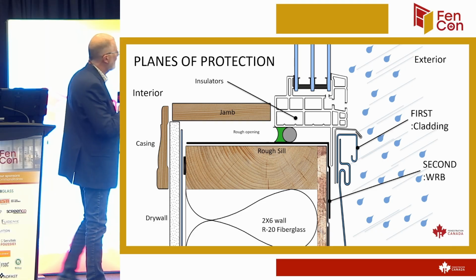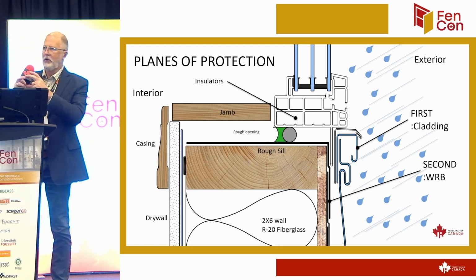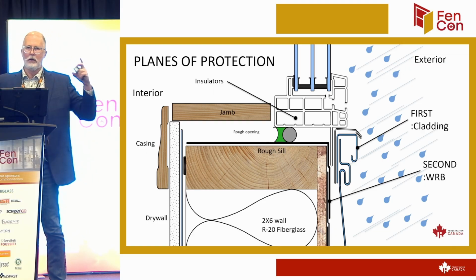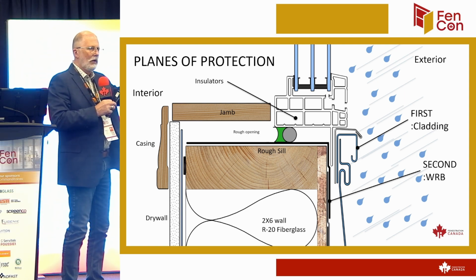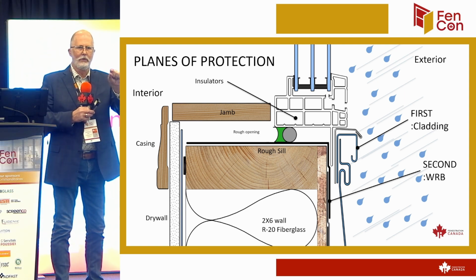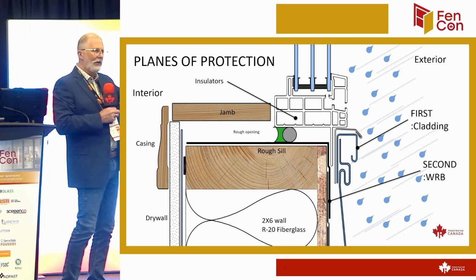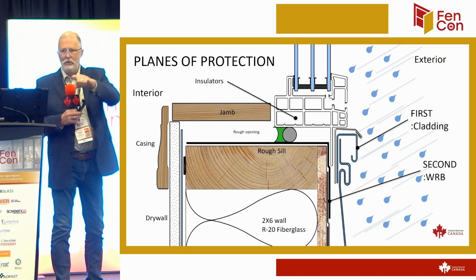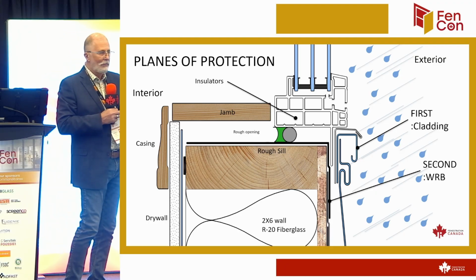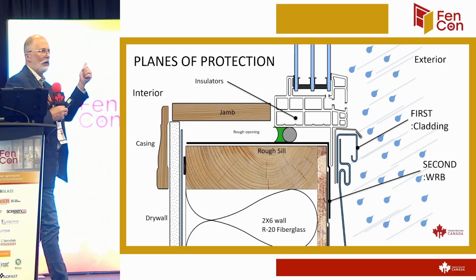Right, so there's insulators here, these empty cavities in your vinyl windows which separate spaces. So if you're getting convective looping, it's not interconnecting to the next one and the next one and the next one. If you had just one big empty space, that convective looping would bring cold air right to the face of the window on the inside. But because they're each individual small ones, it's the same principle as an IGU, right?